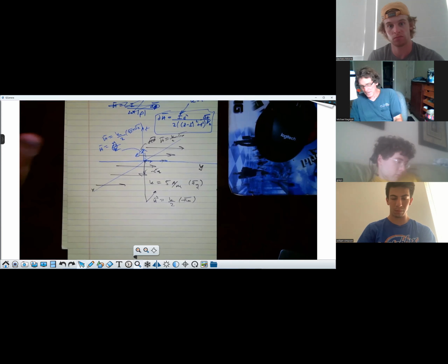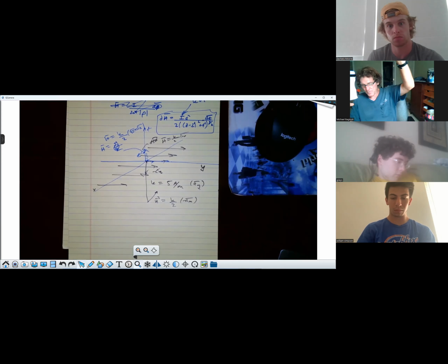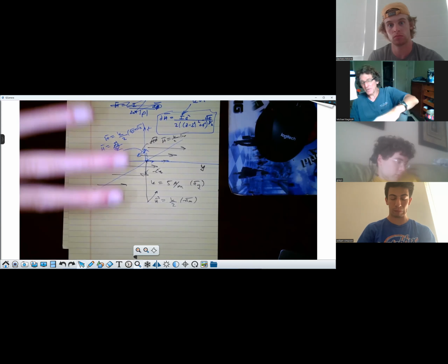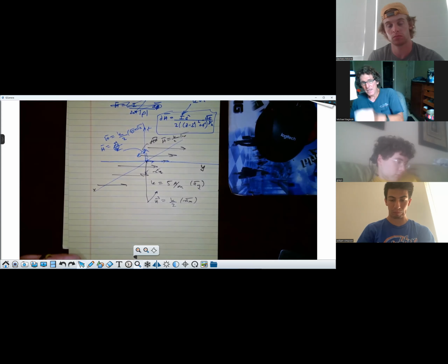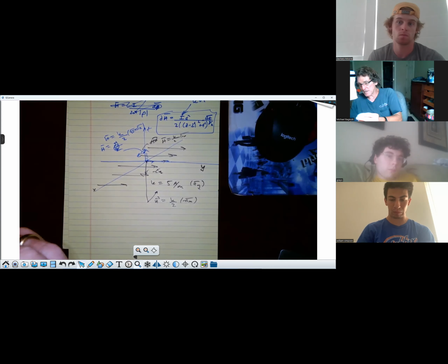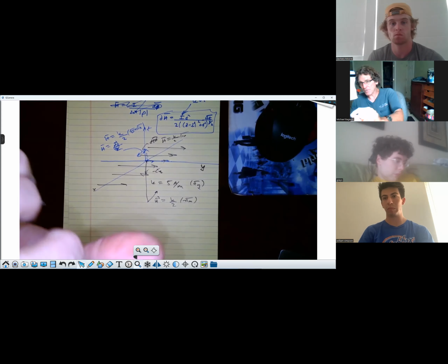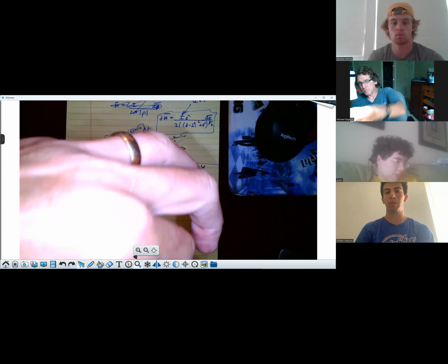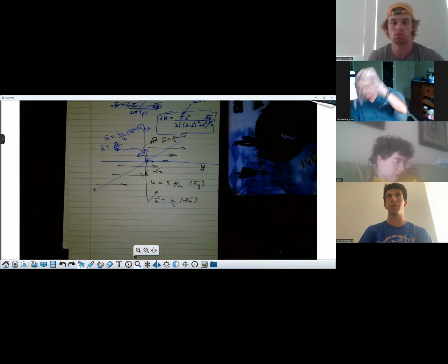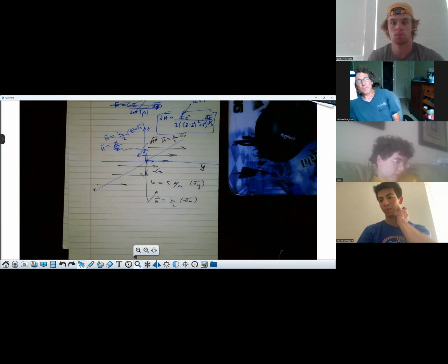We had this grid that we charged up with capacitors that were enormous. We could get a couple million volts, and we had a wire grid about 20 or 30 feet high. And under there, we put this multiple launch rocket system. Where we wanted this pseudo lightning to attach when you charge up the capacitor, we put a paper clip on the thing, bent up one end, and taped it, and the lightning would hit that point all the time. And then we could measure the actual induced currents using B dot probes.